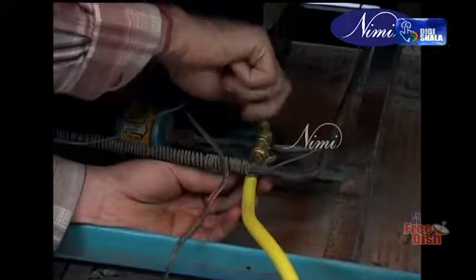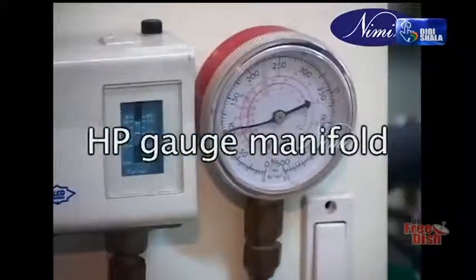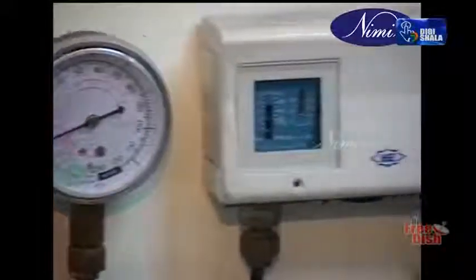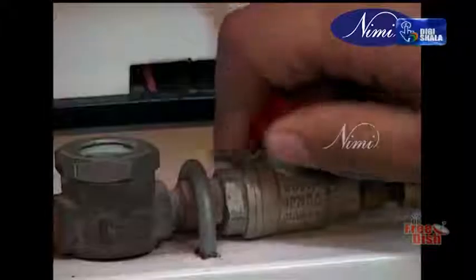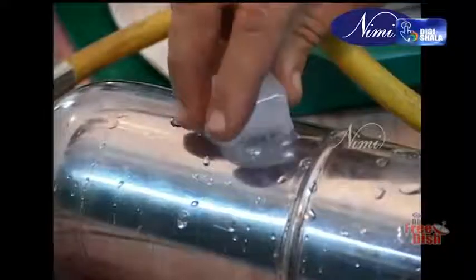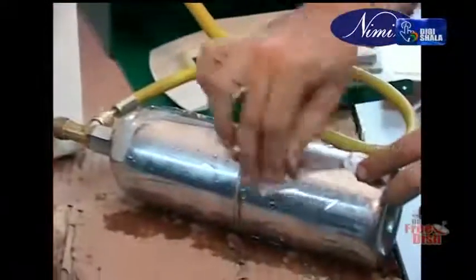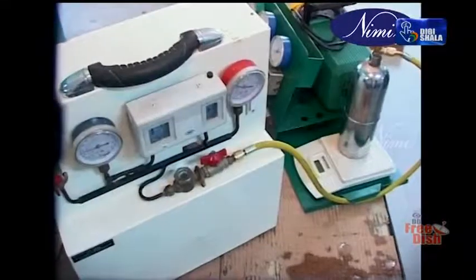Position the other piercing valve on the liquid line HP side and connect it with the HP port of the manifold. Now start the recovery machine. Open all the valves of the manifold. Open the valve of the recovery cylinder and keep it cool. And weigh the cylinder immediately. Close the valves. Check the weight. Whole of the refrigerant should be recovered.